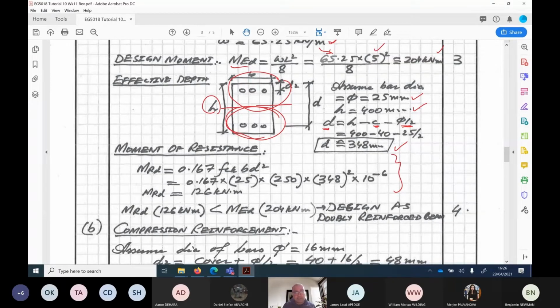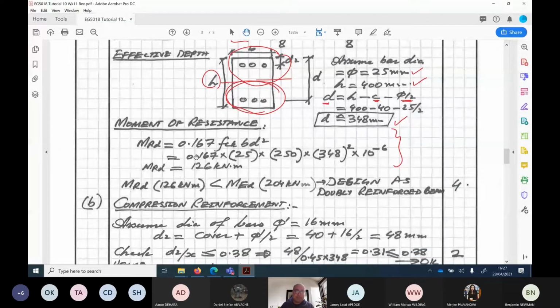And the tension strength of concrete itself, although it is 10% of its compressive strength, it means that if it is 25 Newton per millimeter square concrete, its tensile strength is going to be 2.5 Newton per millimeter square. But that's really very low strength for tension. And sometimes it is even less than 10% of its compressive strength. So it's always better to ignore the tensile strength of concrete. And in all these design calculations, tensile strength of concrete is ignored. Thanks. This actually determines whether we need compression reinforcement or not.